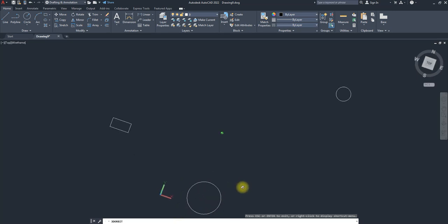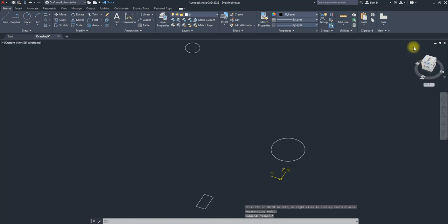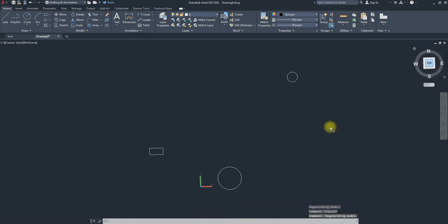So if I click, I can do a 3D orbiting. Right? So that's what orbit does. It's more like me moving around the shape, not in 2D space, but now in 3D space. So anytime you do your orbit, you want to always come back to your home. So when I press escape, you want to come back to your home, then go to your top.